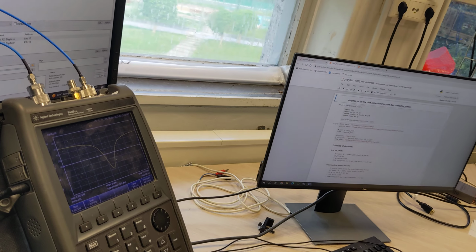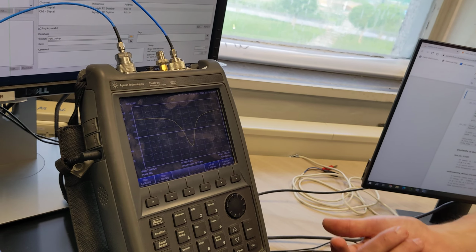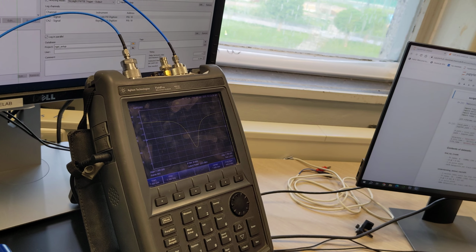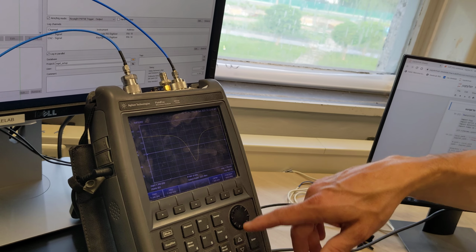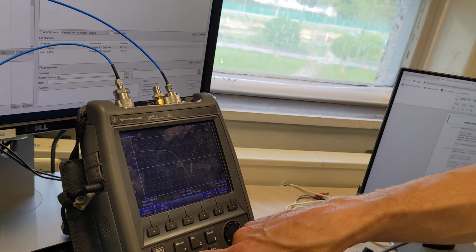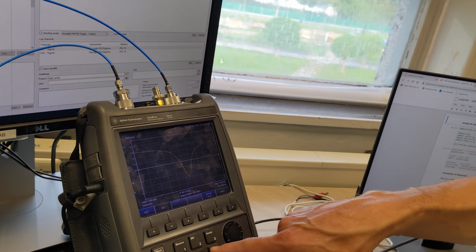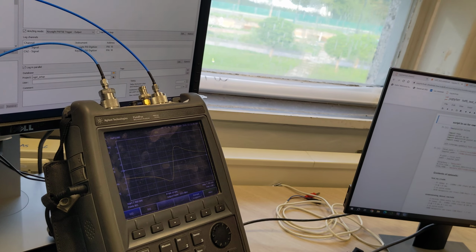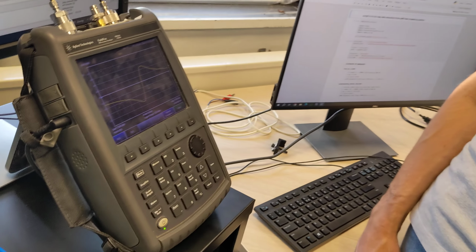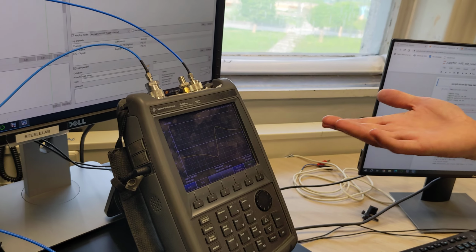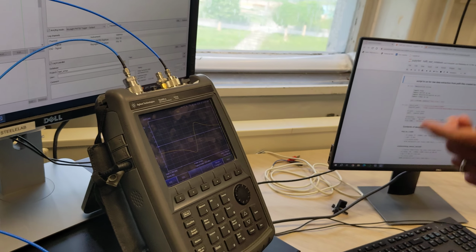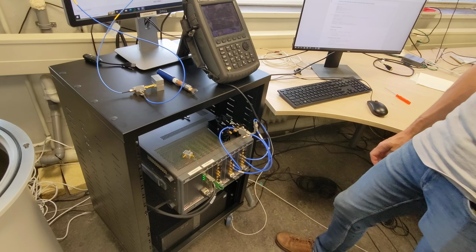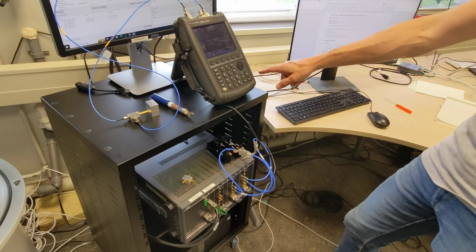That's what we should see if we do it properly and do the electrical length correction on the quadratures in Python for the real part. And then if I go to measure format imaginary, that's what we should see in the imaginary part. And so then the next question is, do we see that when we hook it up to our IQ up and down converter, which will be the next movie.